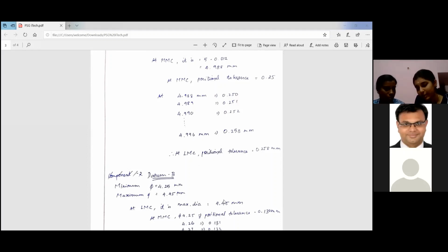So here, the side which is marked as datum A is chosen as the primary datum, and a flatness tolerance of 0.1 is given. Next, we chose the other datum features, B and C, and we give a perpendicularity tolerance for those two surfaces, and then we'll mark the dimensions. Initially we'll mark the dimensions without box.